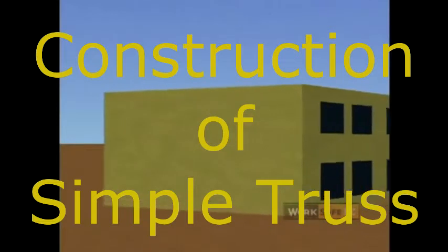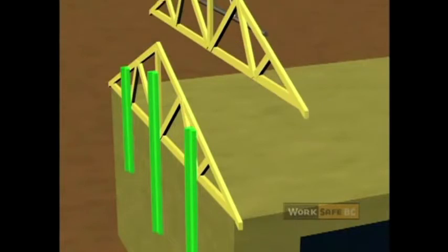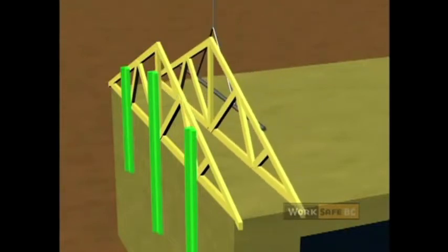Truss structures are composed of members fastened together in such a way as to resist change in shape as a rigid structure. Each member is straight, of negligible weight, and joined at its ends only. The center lines of the members lie in one plane called the plane of the truss. The center lines of members meeting at a joint are concurrent. Members converging at a point are joined by a frictionless pin set perpendicular to the plane of the truss.